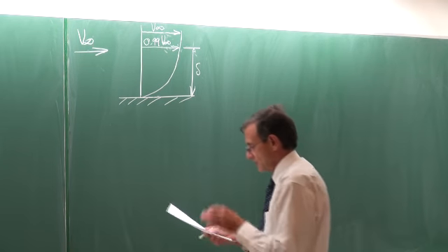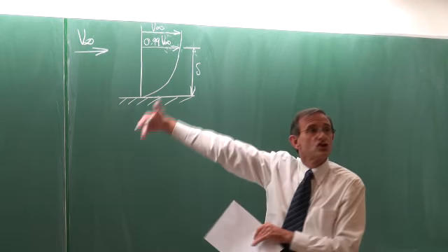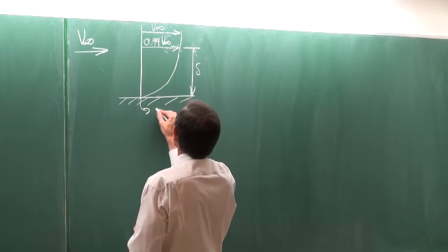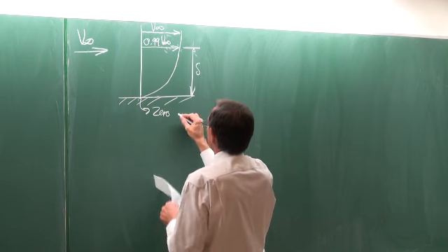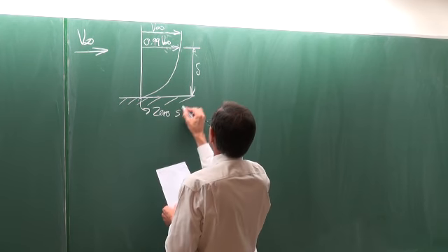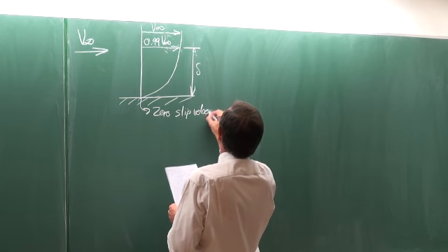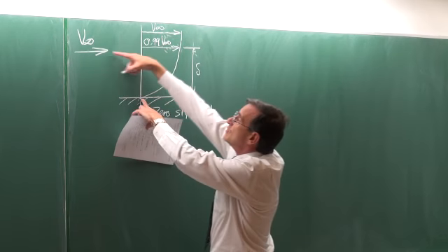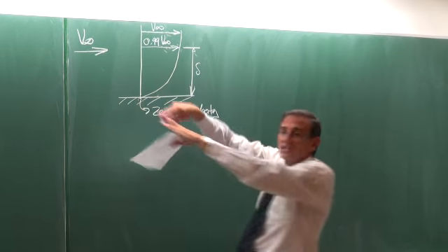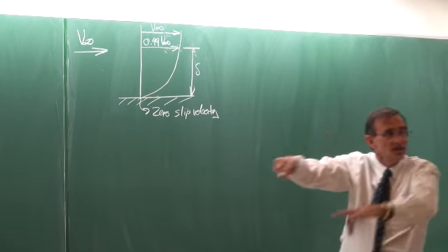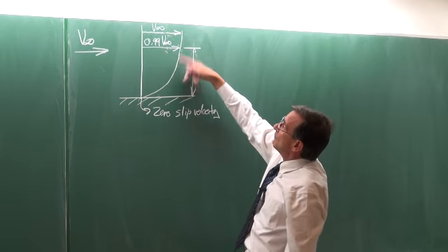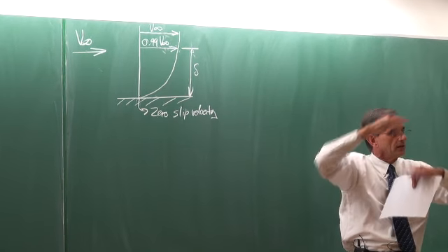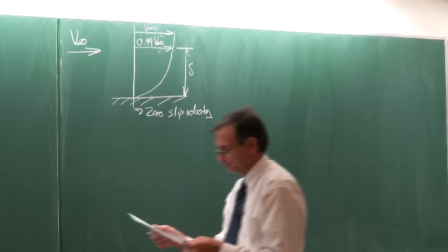That is being caused by viscosity, and also the fact that the velocity at the surface must be 0, which is also called the no-slip condition. So the velocity there is equal to 0, there it must be equal to the free stream, and in between there's a variation in velocities, and where the velocity is 99% of the free stream, that is the height of the boundary layer thickness.